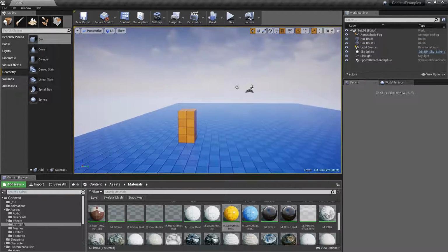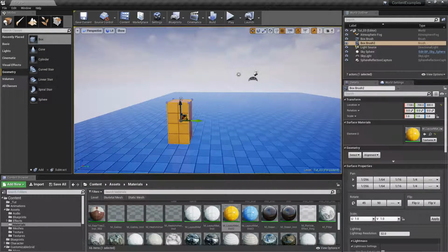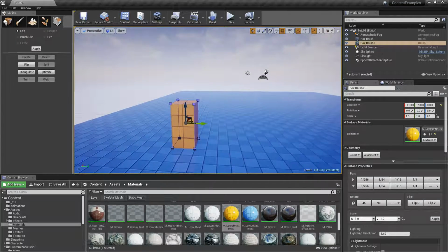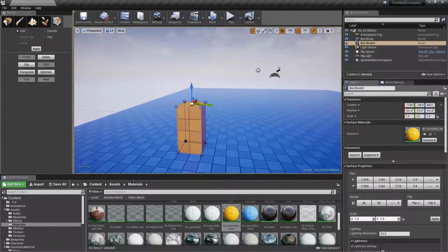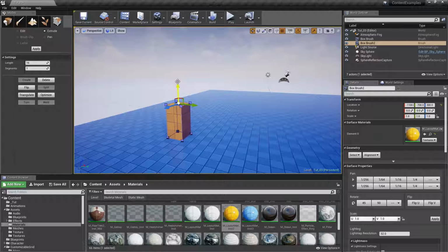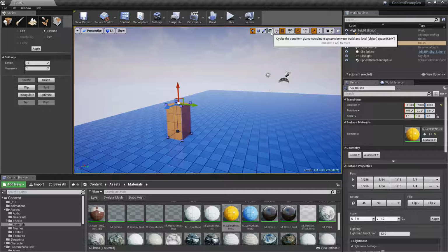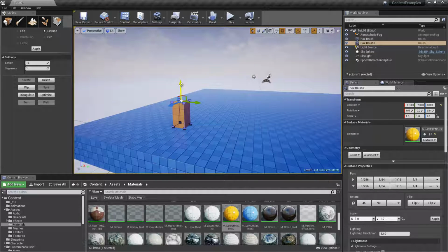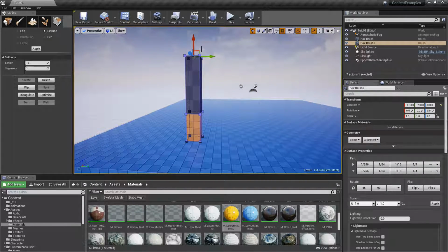Okay, let's do extrusion. So, select your brush, go into brush editing or press Shift F5. You have to select some face to get started and click extrude. If you're doing this for the first time, I already messed around with extrusion before. If you do an extrude, it's going to ask you if you want to accept that it's only in a local space, but that doesn't matter. That's talking about this. So if we bring this further up, we're going to make it bigger, right?